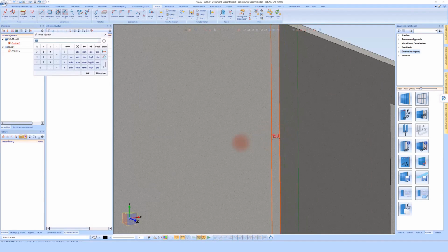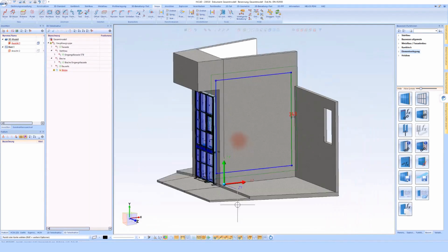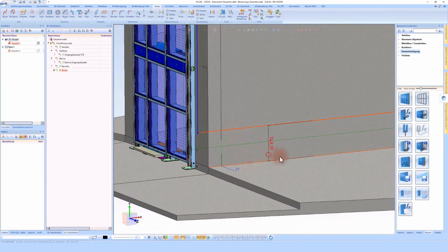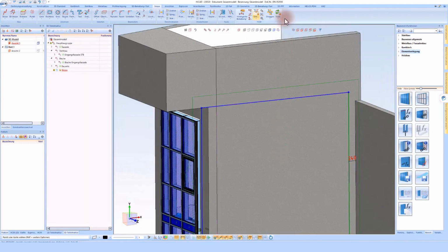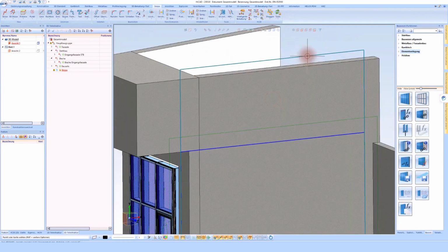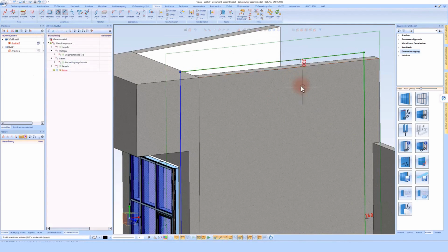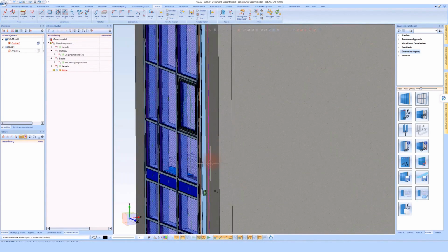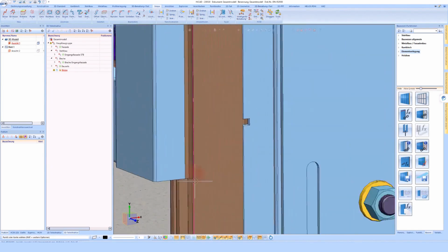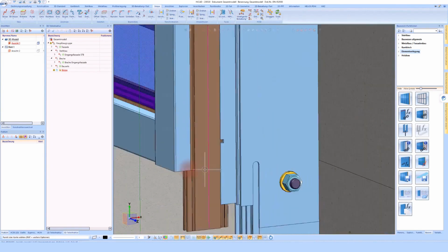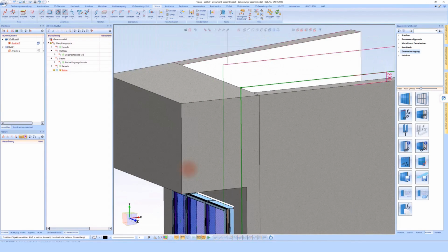I set my measurements. This means I specify here my values for where my facade should start or end. The upper edge. In this particular case, my items should extend approximately 200 millimeters in this area, and to make it significantly easier for myself later on, I want to precisely align with the glass edge.